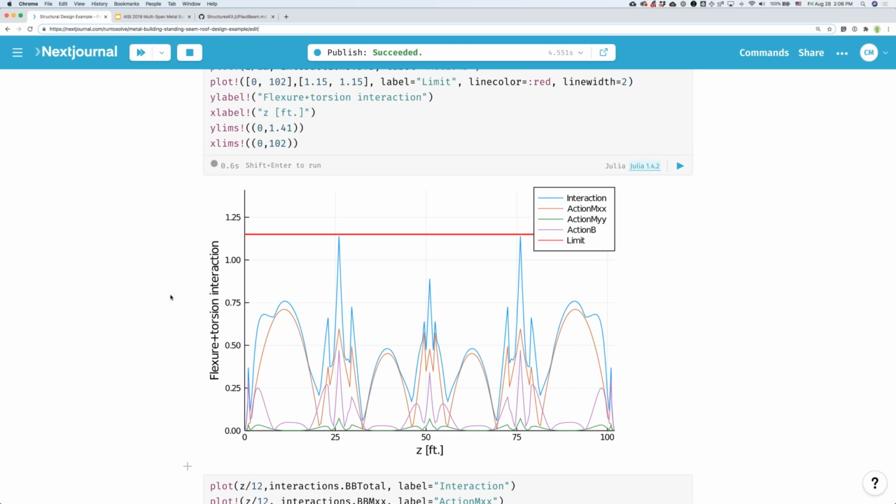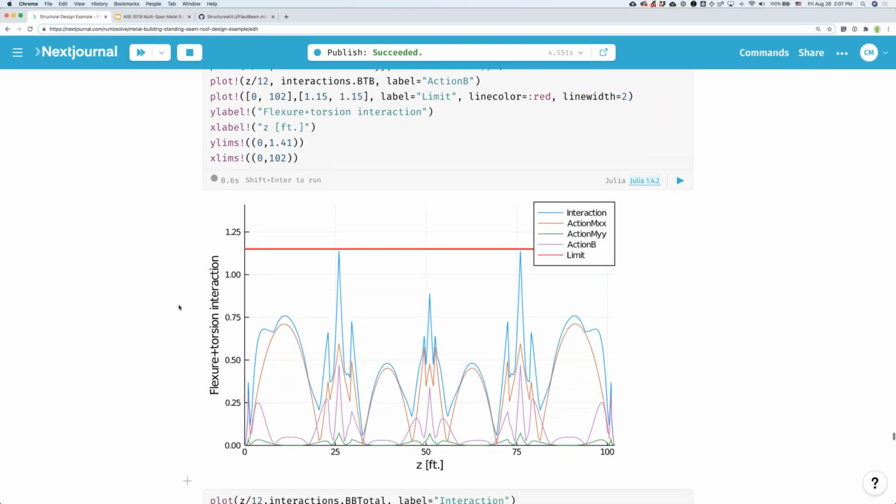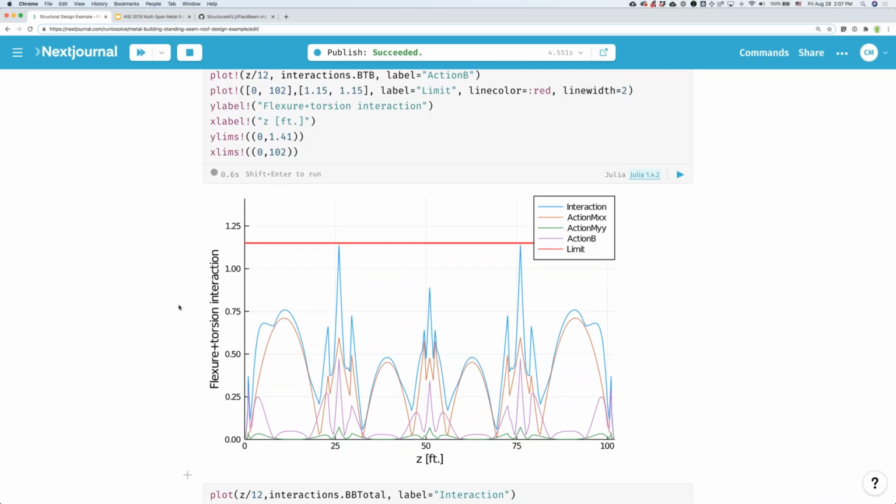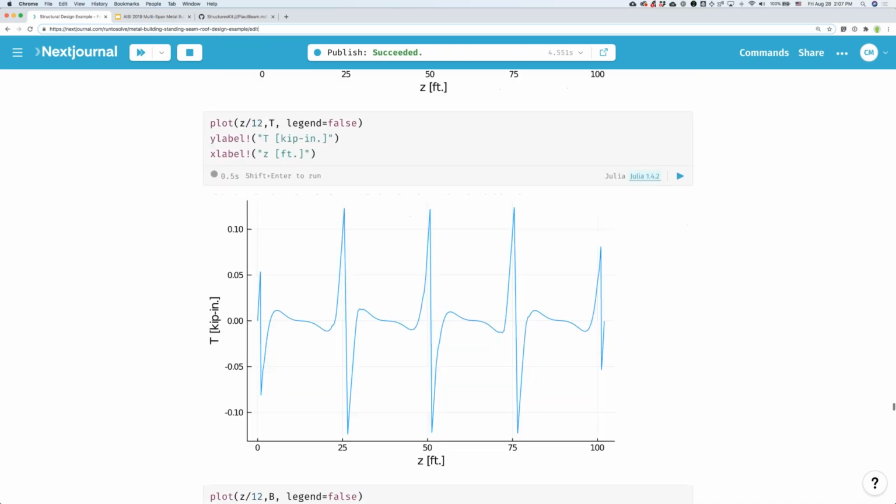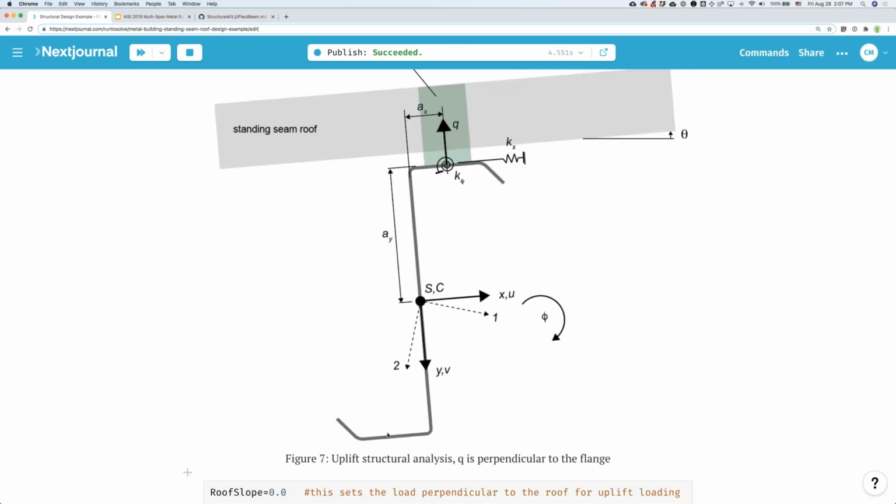So this is different than what I would have expected. We all think of an uplift case where the exterior span would go. But I think there's barely any uplift tests for multiple spans. We'd have to dig around for the simple span uplift tests that I've run. For sure the purlin wants to roll sideways. When you put this piece in compression, it wants to buckle this way.